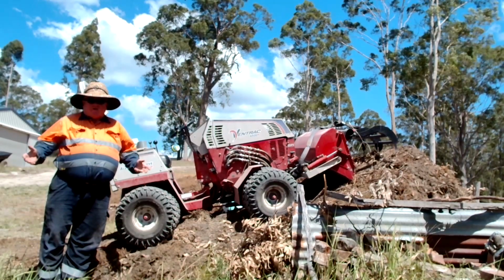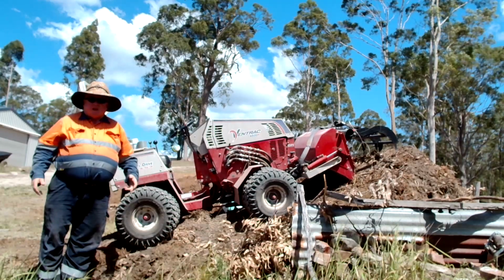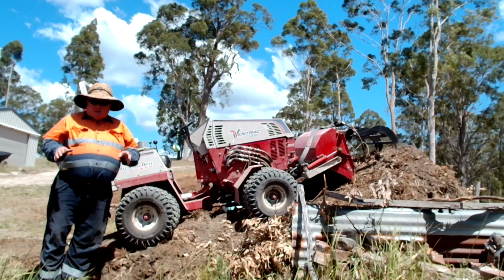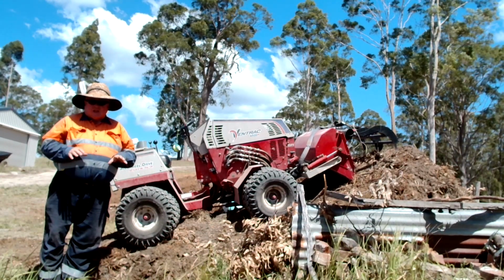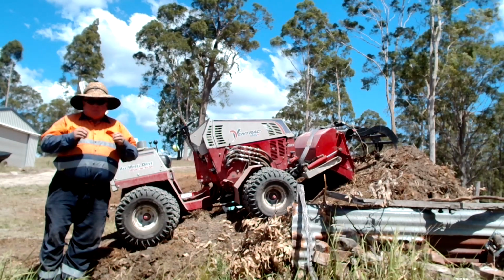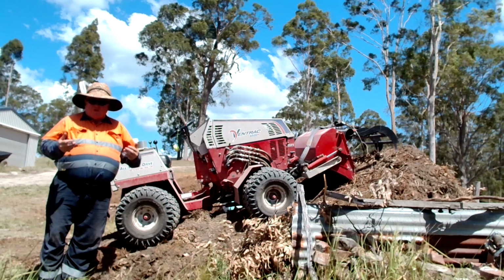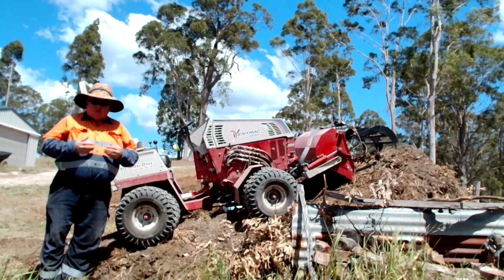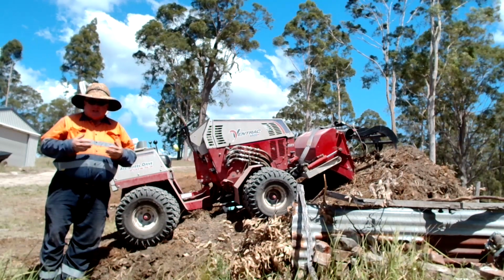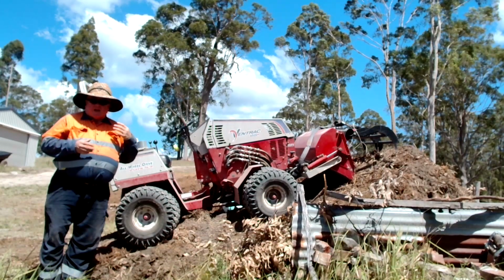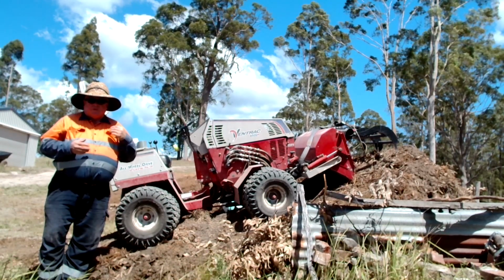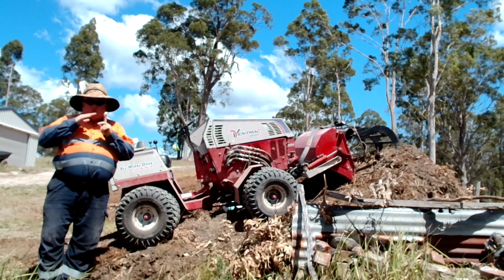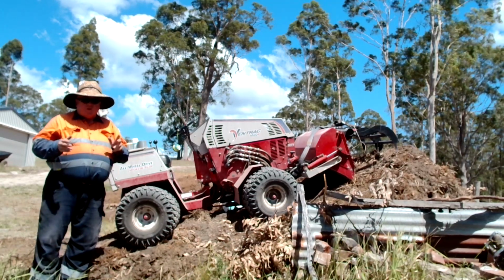So here we are back on the farm on a beautiful autumn day. It's about 31 degrees and a little breeze that I hope doesn't upset the microphone. I wanted to use some real world examples of grades, because talking about grades on paper is one thing, experiencing them in reality is another. We're going to use the Ventrac 4500P as an exemplar again today, and I have it parked here on a 15-degree slope. Now that's 1 in 4, 1 up for 4 horizontal. So 1 in 4, 15 degrees from the horizontal, roughly.